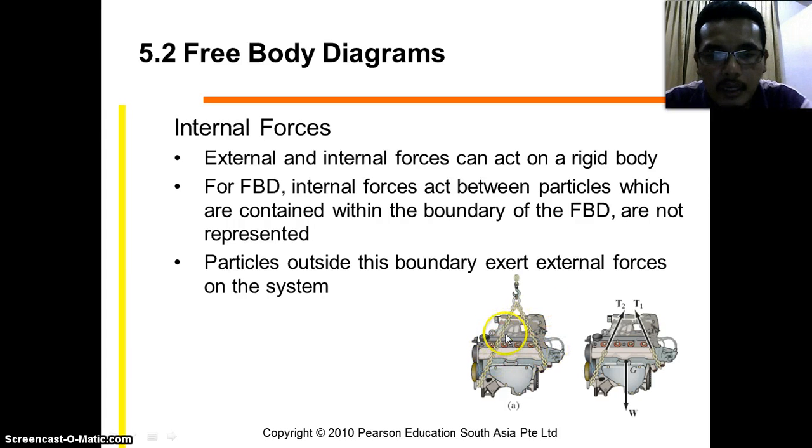Then we hook these two cords, and at this one is the screw eye here. So if we want to get the tension of this cord, and also we need to find the reaction at this hook, for example, for this separation, what will be the internal force? Is it affected or not? So the internal forces are not represented. We only consider the particles outside this body as external forces on the system, for example, these two tensions.